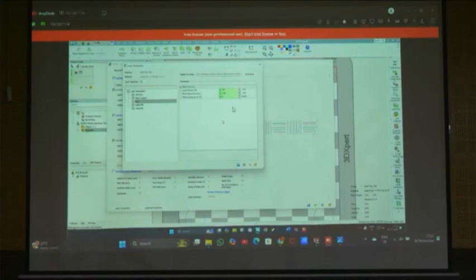He just did the parametric optimization and got one parameter, and he is playing with the design, applying different structures and testing them, and whichever gives the best results, in terms of Young's modulus as well as, if anyone knows the lattice structure testing terminology, plateau stress and energy absorption. Energy absorption means toughness, as in a solid body.